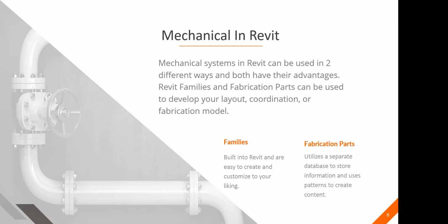So now you're modeling with actual parts and pieces that you can cut on your CNC plasma cutter. The power behind that is not just the power of Revit, where you're adjusting a model instead of drawings, but that you can build that model with fabricatable parts to scale. So it's no longer just a 10-foot duct. This 10-foot duct now has all the cuts, bends, and profiles I need to create the connectors at each end.